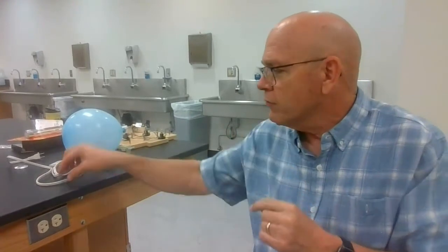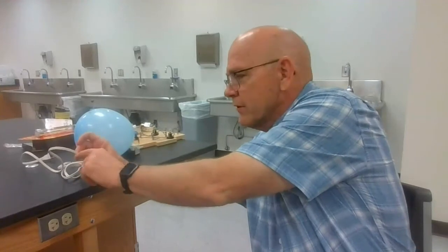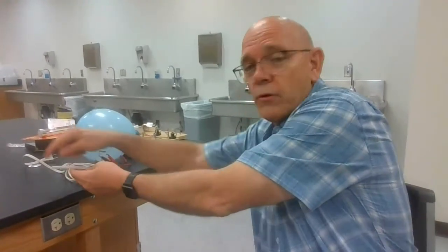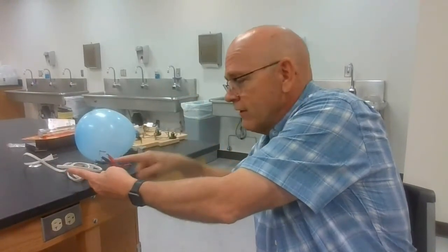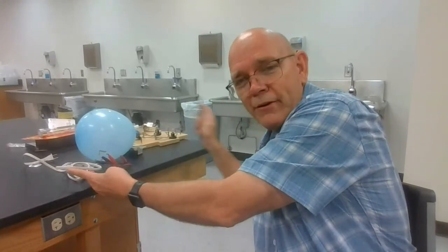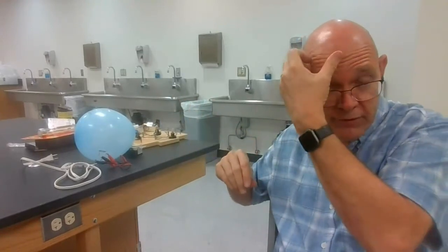And so that reduces the amount of current because you have a high resistance. But say you have two wires in your cord and they touch inside here. For some reason it gets cut or something like that, and they actually touch each other. Now instead of going to your appliance and coming back after it has been reduced by the resistance, it just takes a little shortcut, jumps back here, and goes straight back to the circuit with no resistance reducing the current. So you get a high current, and it just keeps going back and back. It takes a short circuit, and therefore it's very dangerous and can build up a lot of heat. This is also another thing that fuses help protect us from.